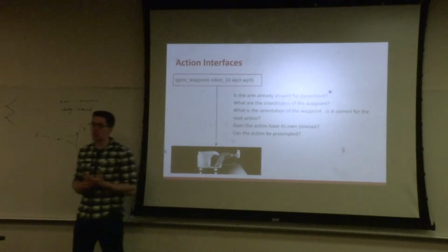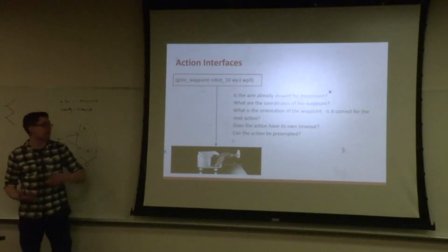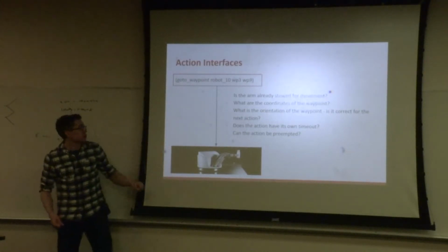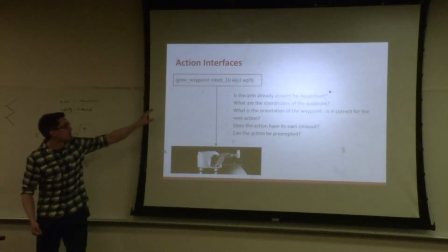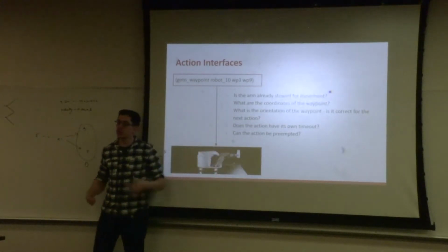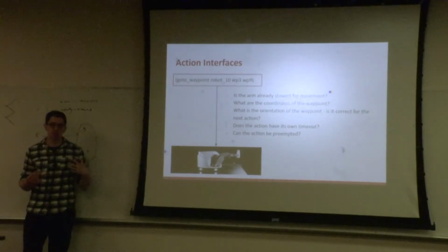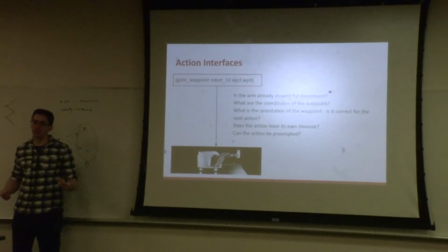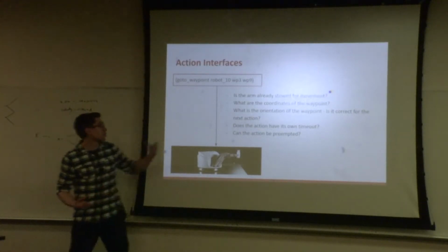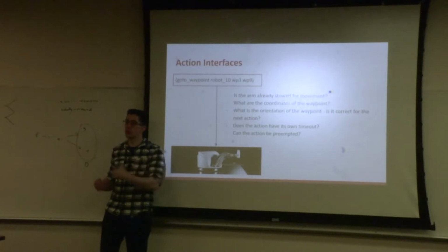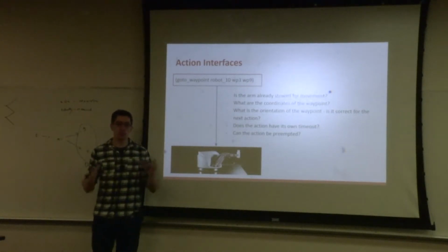That's not a process that could be easily automatically generated, this connection. Second, what are the coordinates of the waypoint it's going to? Here it says waypoint 9, but the navigation planner doesn't know what waypoint 9 is. It requires you to call a service, and the input to that service perhaps is the exact coordinates you want the robot to move to. So you have to first of all replace go to waypoint 9 with the lower level description of move the robot base to this position.